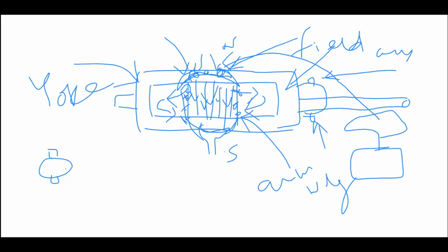Similarly, the magnetic field has the former in which the slots are there, and in these slots the field coils are placed, and the pole arc is separately connected to it so as to give the desired path to the flux. What else is connected centrally is the fan system.